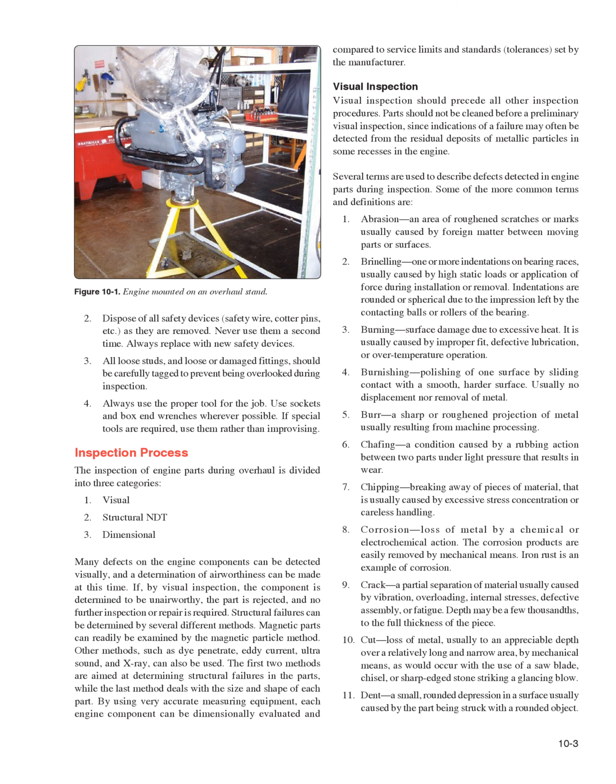Visual inspection. Visual inspection should precede all other inspection procedures. Parts should not be cleaned before a preliminary visual inspection, since indications of a failure may often be detected from the residual deposits of metallic particles in some recesses in the engine. Several terms are used to describe defects detected in engine parts during inspection. Some of the more common terms and definitions are: 1.